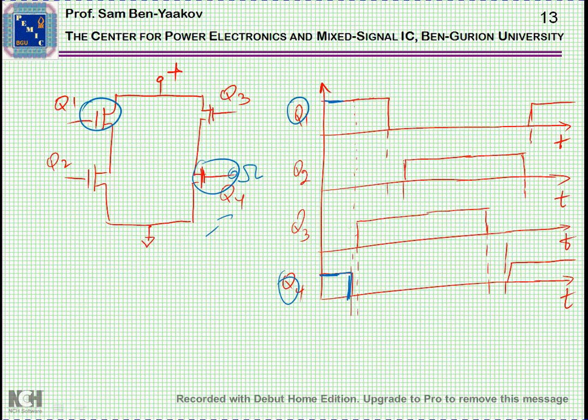And after a while, as this voltage goes up, the diode is clamping, I would like to turn on Q3. Here is Q2. All this time Q1 is on. At a given point, I'm turning off Q1, releasing this point to go down. So here's Q1 down. And after a while, I'm turning on Q2. So this is Q2. So as you can see, these are sort of funny looking waveforms.